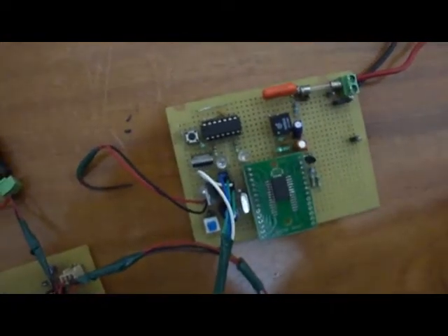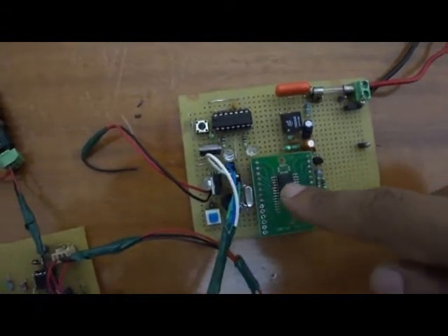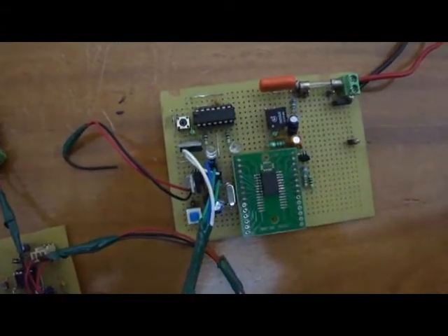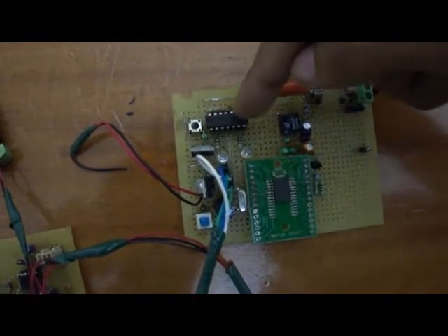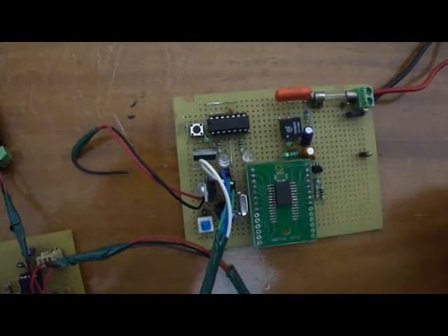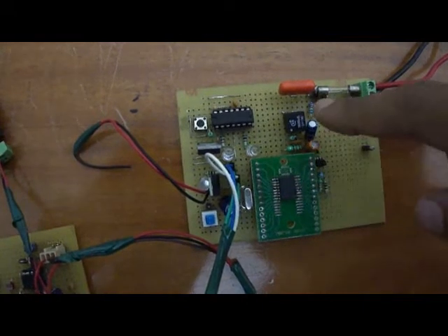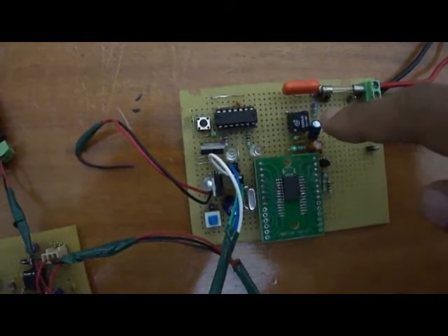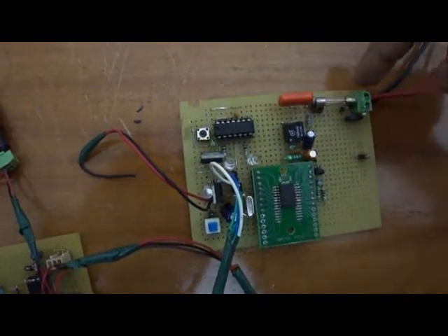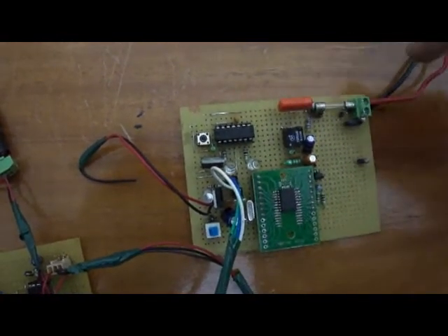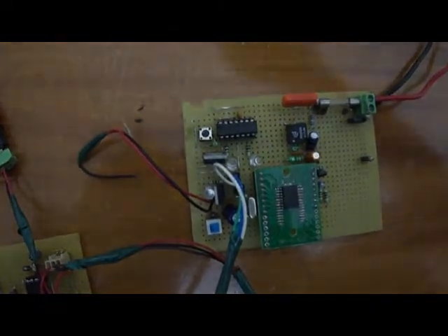What this board consists of is a PLC ASK modulating IC, which is a TDA5051. This is the voltage regulator. There's another MSP here, but that's just for testing purposes. We are not using it with the light module. The TDA IC is connected to an isolation transformer by Murata, which connects to the outside power line. This is basically the circuitry for protection, the fuse, and these two wires take us to the power line.